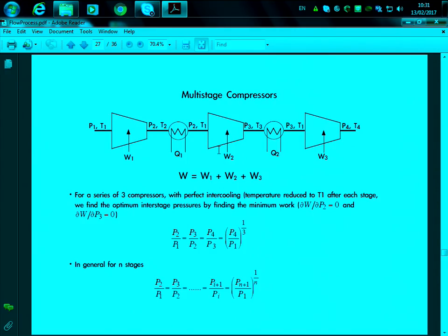So in this case, we will have these compressors coming together, and here what we're basically doing is controlling the temperature. We do an incremental increase in pressure, so we're all the time applying more pressure to the system, but the temperature will come back to the initial conditions through a heat exchanger.